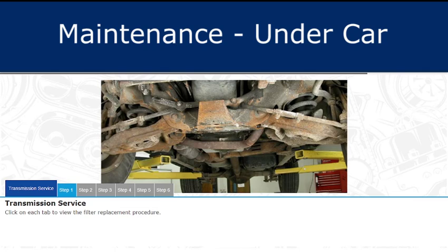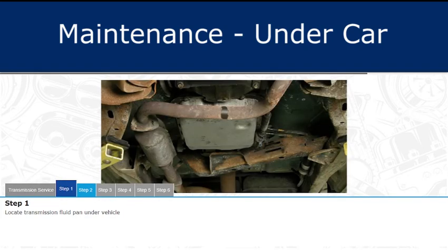To view the transmission filter replacement procedure, select each tab for more information. When finished, select Next to continue. Locate the transmission fluid pan under the vehicle.